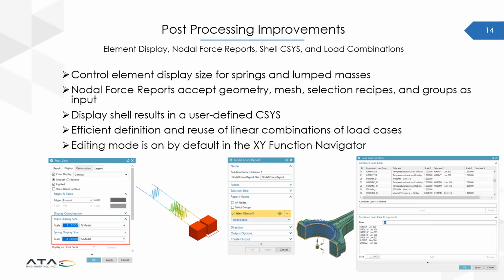And closing out with these last 2 bullets, there's a new way to more efficiently, and with the ability to reuse, linear combinations of load cases. Now this is limited to linear static loads, and the way that it's set up, you have to have subcases all within a single solution with global constraints. But you end up with the ability to create a table like this, and you can do different scale factors of your different load case subcases. So we'll take a look at that as well.